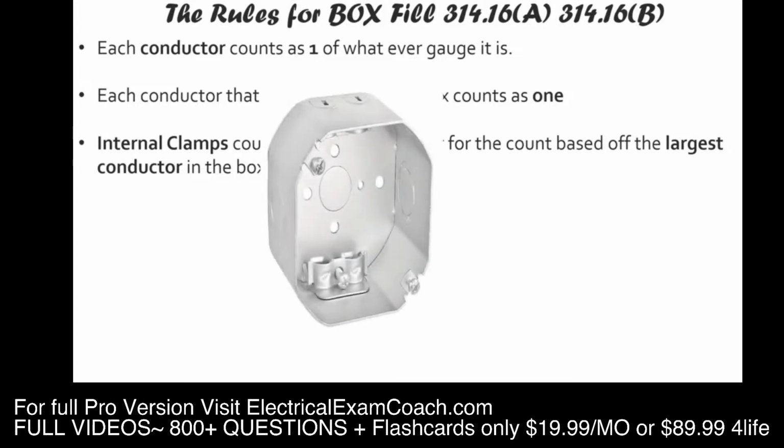This is an internal clamp. The clamping mechanism is inside the box. Well, it's taking up some of my space, so we have to account for it somehow. What this code is stating is it doesn't matter if I have 1 or 5 of these clamps, we're only going to count it as 1, and it's going to be grouped with whatever the largest conductor is in the box. Meaning if I have 12 and 10 gauge conductors inside that box, this internal clamp would count as 1 10 gauge conductor.